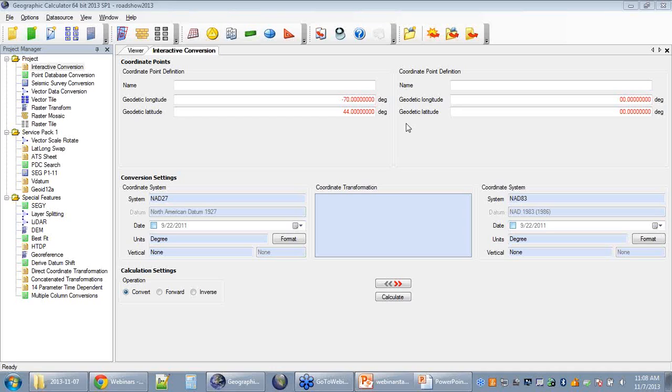For the last many years now, though, we have been in what's called a late binding model. That's a technical term that just means the coordinate transformation is a separate selection from the horizontal datum itself. So we dynamically select the best coordinate transformation for the combination of input and output systems.